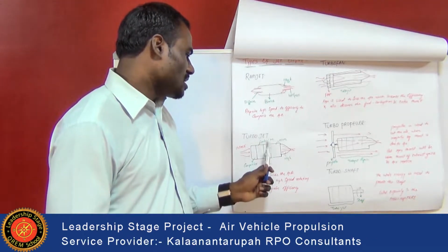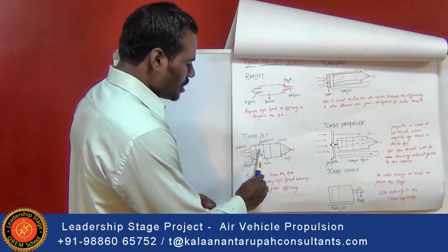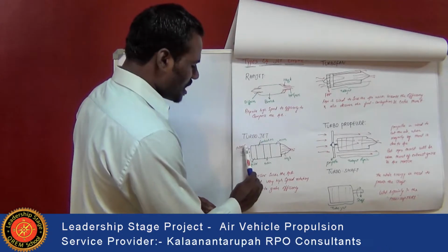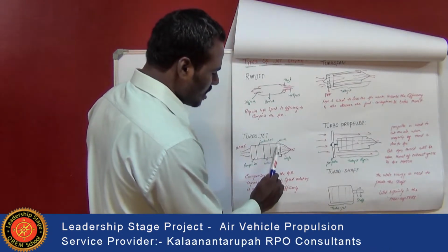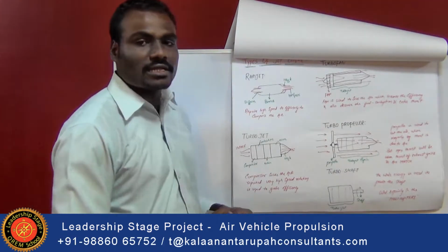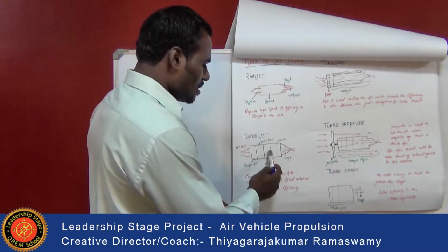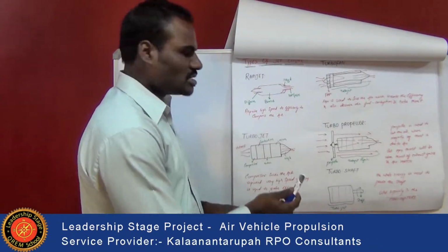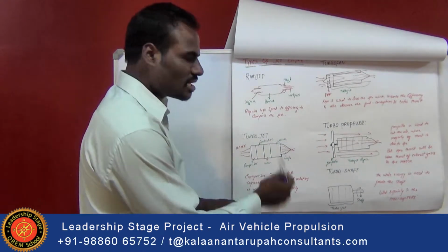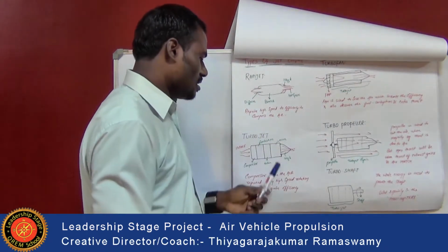exposed from the combustion chamber, and the mixer. In the sense here, some of the gases will be entering into the combustion chamber, and the exhaust will be released at this area, whereas most of the air which has been sucked inside the nacelle structure is subjected inside the nacelle structure. Here the mixture area is the area where the afterburner process is carried out. The gases which are coming out from the turbine and the air which is flowing inside the nacelle structure get mixed up, and it is ignited here. In order to get a better thrust, we use this kind of afterburner process.